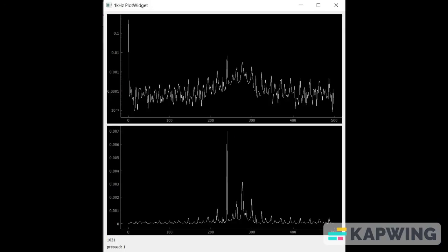If you look at a plot of the two graphs in the frequency domain, the top being the unfiltered signal and the bottom being the signal filtered out for 50 Hz noise and the DC component, we can see for the button 1 being pressed that the signal is a lot less noisy, and we can see two fundamental peaks for the button 1. Each button had their own two fundamental peaks matching up to the rows and columns. We used these peaks to figure out what button is being pressed.